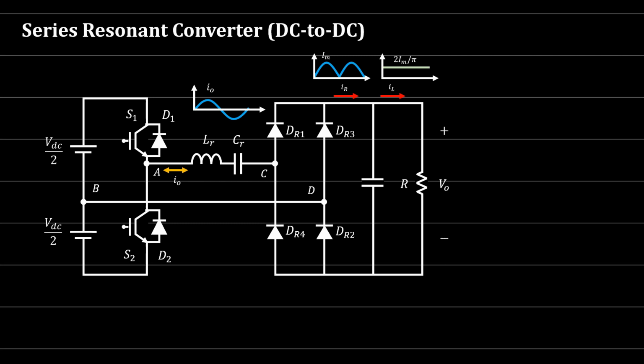It depends on two factors. Number one, the components, the load resonant components, the resonant tank, which is the capacitor and the inductor, okay? Number two, the value of the frequency. Once we pick the capacitor and the inductor and fix the frequency, we will not be able to change the value of the frequency, right? Otherwise, we have to change the value of the capacitors and the inductors.